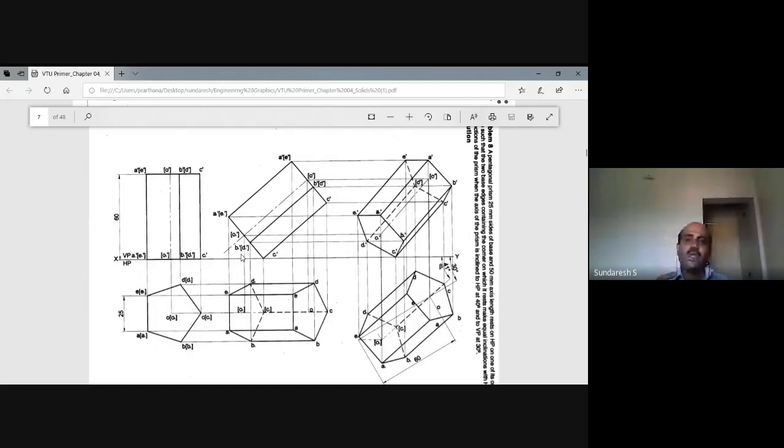A very simple way to show the invisible edges is to look first at the corner or the edge which is away from the observer, and the edges which arise out of those points should be considered as invisible edges, if they do not form an outline. This is a very simple logic, a very simple way where you can represent the invisible edges in our solids.